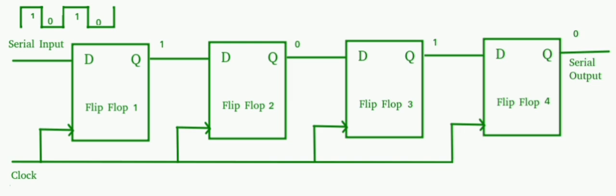R-2R ladder DAC using an inverting op amp. The output voltage V0 = (Vreference/2^n) × Σ (i = 0 to n−1) 2^i Bi × (−RF/3R). Output current I = (Vreference/2^n) × Σ (i = 0 to n−1) 2^i Bi × (1/3R). The resolution of the R-2R ladder network is VR/2^n.